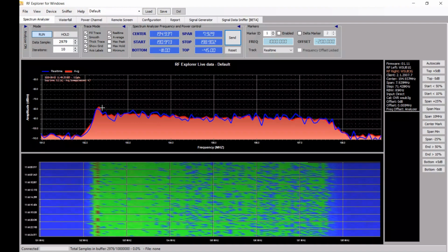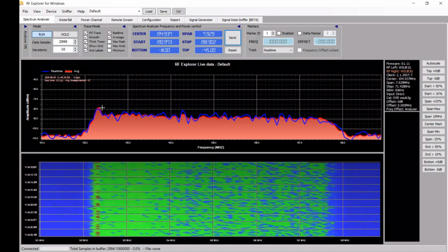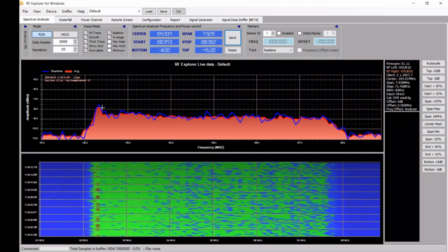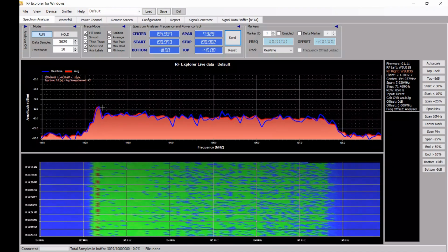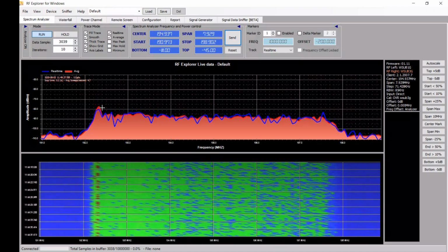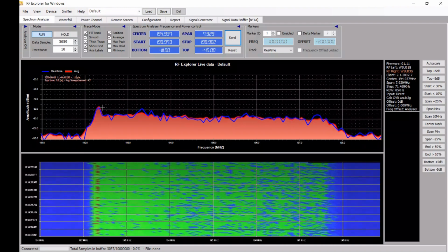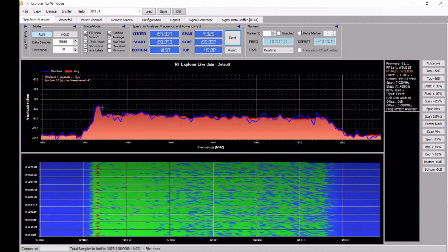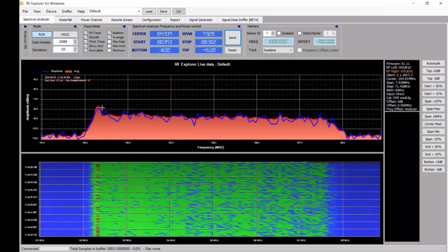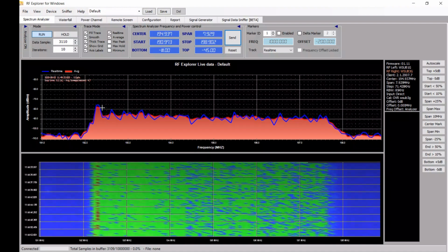There are devices called distribution amplifiers. They are an amplifier and splitter combined into one, and their specific purpose for existence is to split the signal of one antenna to serve multiple receivers. That's a case where you might use one, because while you're degrading the signal to noise ratio, you are making the signal hotter. So by the time it reaches the receiver, you have a usable signal.